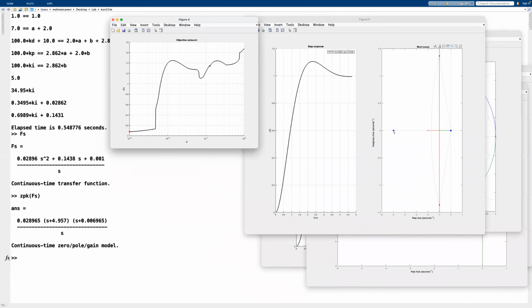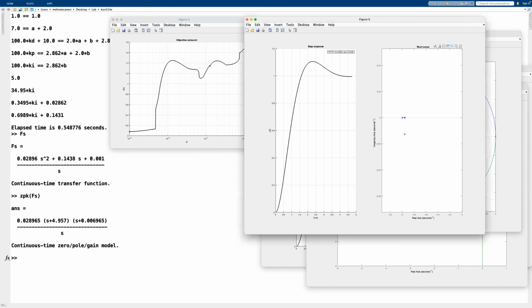If you're somewhere at 5, and if the controller structure is basically canceling the pole zero, which in this case is not a pole zero of the system, this is a good example. This could be used in a real world application. But for example, this one can never happen in the real world. And you can see why, because there might be a slight tendency to the right half plane and a little parameter variation would end up in the right half plane, and your system will mess up, and it will become unstable. So pole zero canceling is not always a good thing,